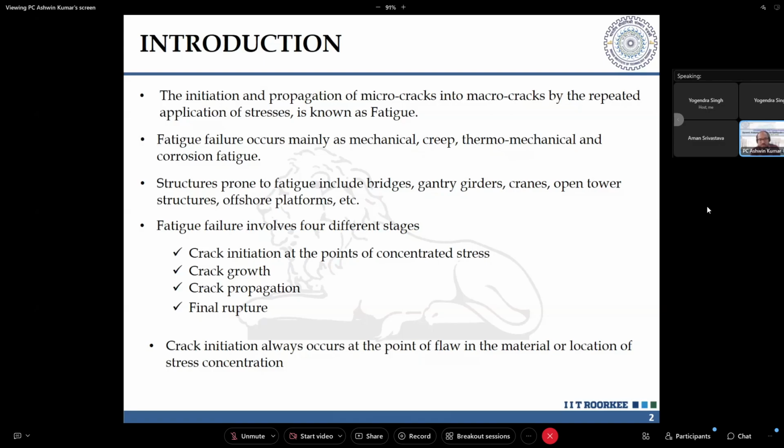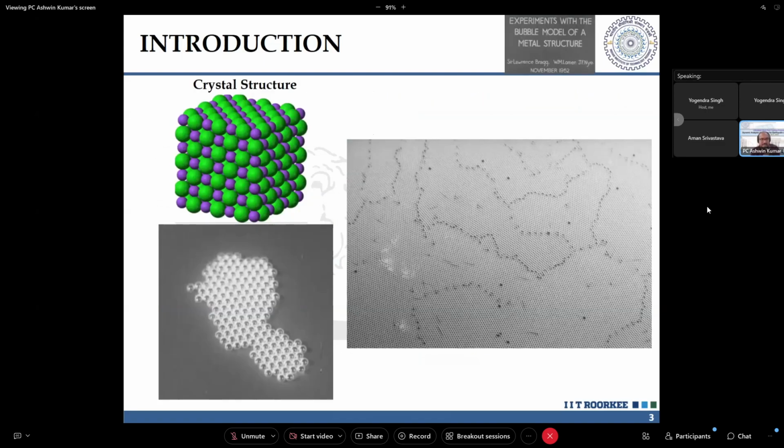In both cases, whether it is a flaw or stress concentration, we are talking about two things happening. Cyclic loading is there. There is a stress range that is getting developed as the vehicle is moving or the wave is attacking the structure. There is fluctuation in the stresses, which we define with the stress range as the important parameter. And then there are localized areas where stress concentration or slip or yielding occurs, right? We'll come to why I said yielding in just a bit.